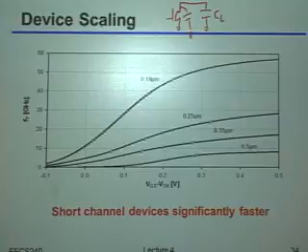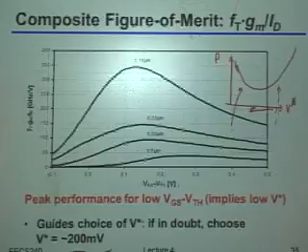Well, if you get to the point where this parasitic is comparable in size to the cap you're driving in the first place, you're going to start spending more power to drive your own parasitic, right? You won't quite get the bandwidth you want, which means you have to spend even more power, and you'll have even more parasitic, and so on and so forth. So at some point, as you get very close to the gain bandwidth the transistor can even support intrinsically from its own parasitics, that's when you start having this explosion in power consumption over here.